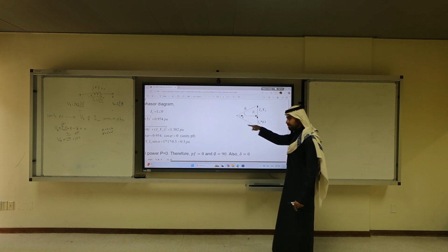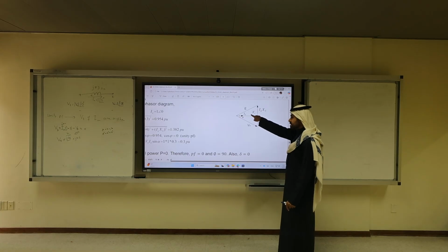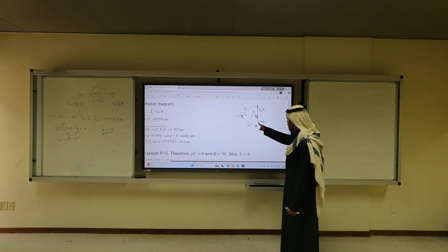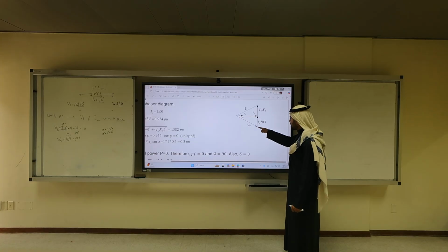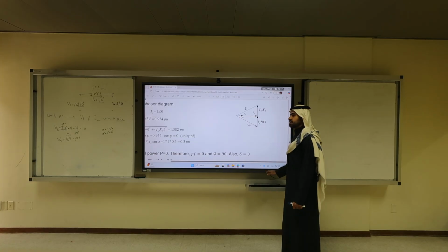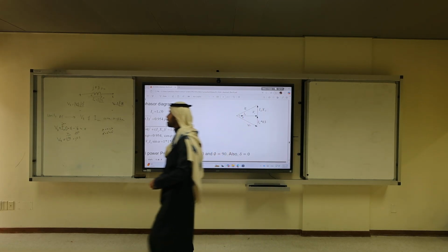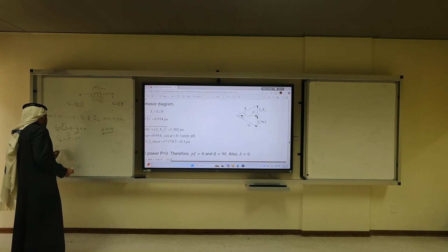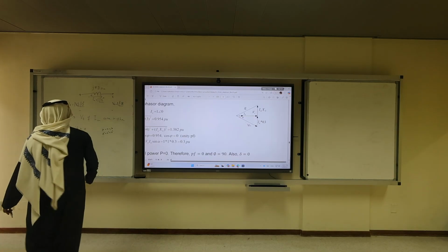So you get a triangle. VB squared is equal to 0.3 squared plus VT squared. Because IA is 0.3, if you add a negative sign, it would be VT minus IA 0.3 equal to VB. That's what I was trying to show here: VB, which is a complex number, equals VT plus 0.3 j, where IA is 1. These are two complex numbers.